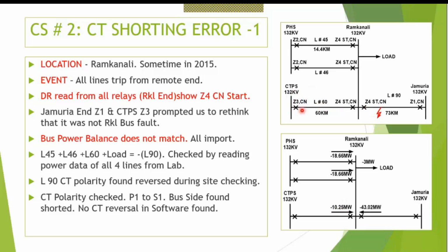Okay, I think this is a very good example to show that overreach and underreach. It should have been zone 2, but it is underreaching and the fault is going into zone 3. Okay, so this is how we understood.